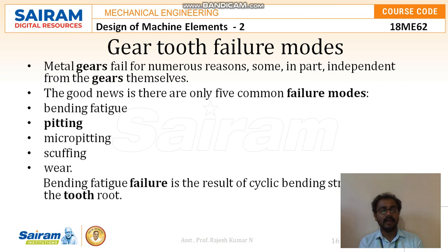The more frequent cause of gear tooth failure is the bending fatigue, which can be avoided by leaving a certain break after the operation, after some cycles. The next one is pitting and micro pitting. Both pitting and micro pitting can be avoided to a certain extent. Then the next one is scuffing, and the last one is wear.